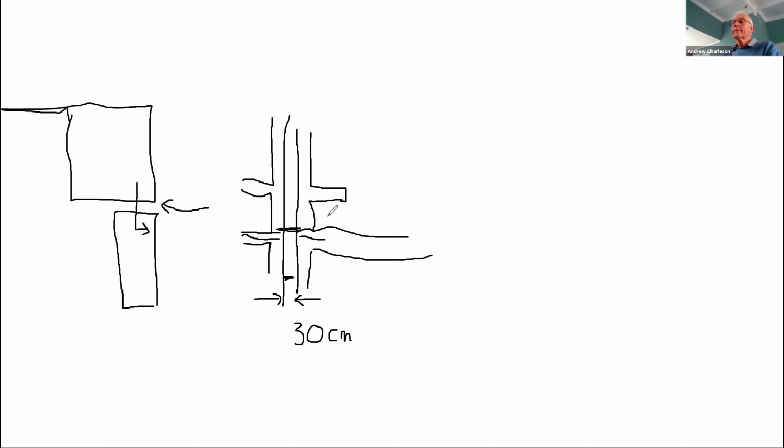Andrew, is it different with dilatation? Yes, it is. A dilatation is really a separation gap to control shrinkage and temperature expansion. And those movements are usually quite small compared with the movements that occur during an earthquake.